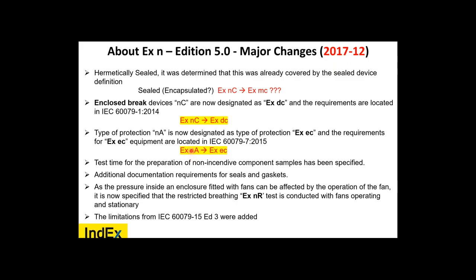NA, remember, was terminals, no arcing, no sparking, exactly the same as EXE. Enclosed break, it's like a bomb-proof safe, flameproof, okay? Enclosed explosion, keeps it enclosed. EXD. EXNC, encapsulation. Well, the word encapsulation is in there, so it became M.